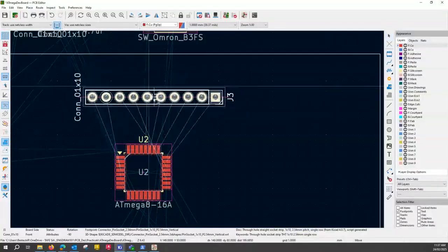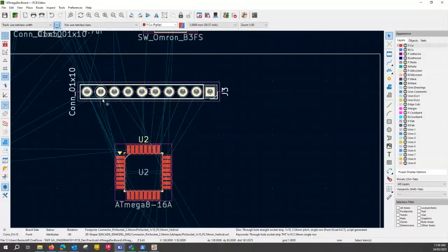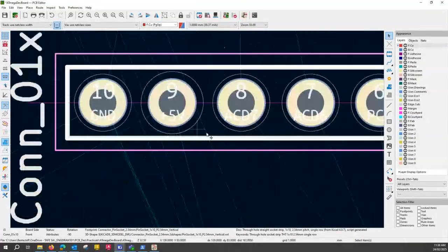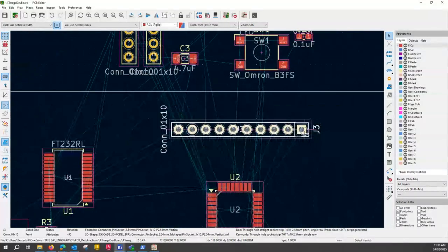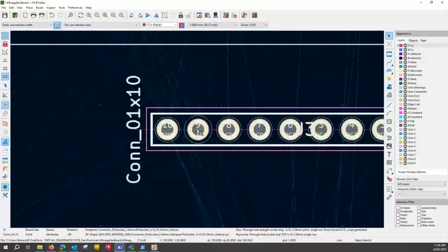You can see that the majority of them connect directly. Some of them connect indirectly. To make it easier, on each of those connectors this is pin 1, and the last 2 pins are 5 volt and ground, so we are keeping it the same across all different connectors.